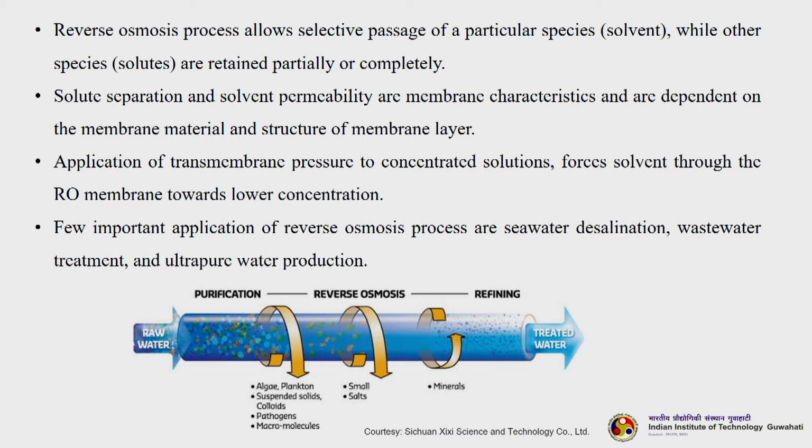A few important applications of reverse osmosis are sea water desalination, which is the most important application of reverse osmosis, then wastewater treatment, water treatment also, and ultra pure water production. You can see from the figure that algae, plankton, suspended solids, pathogens, macromolecules, small molecules, salts, everything will be rejected by the RO membrane, and only solvent will flow through the RO membrane.